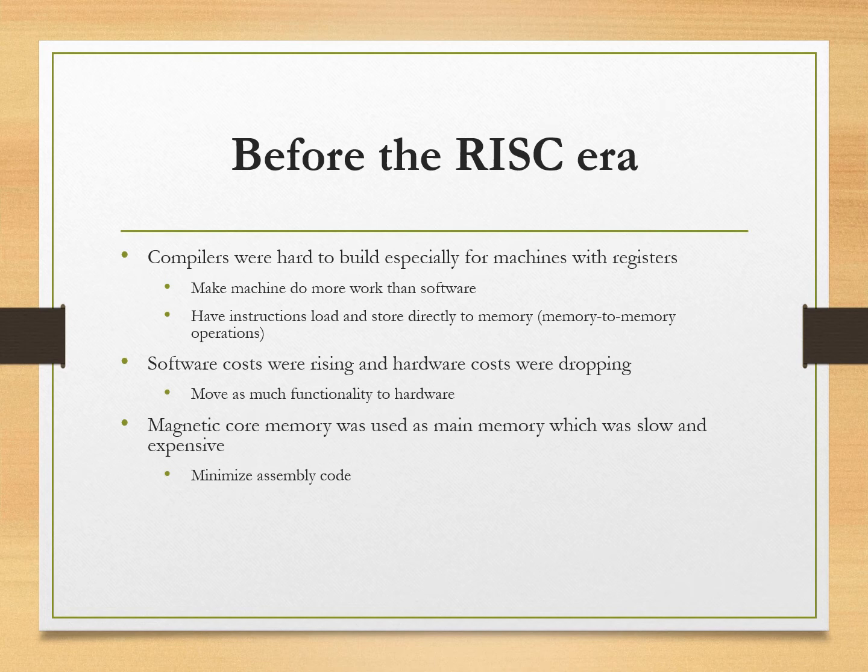So that's why they increase the number of general purpose registers. Even though there may be 1,000, maybe a million registers inside the processor, the general purpose ones, the ones that can be accessed by the programmer, are limited, and there are more than in the CISC microprocessor.